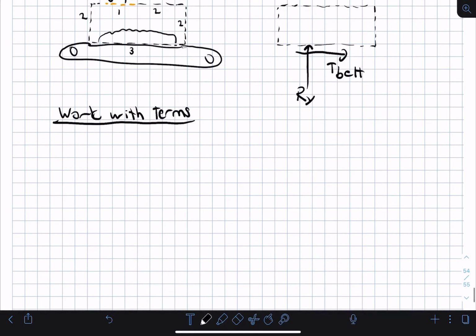Okay, and so we have partial t times the volume integral of rho times the velocity dV in the control volume. Okay, and so here we are only considering the sand, so I'll just do a little subscript s here to note that we are neglecting the air, and I already justified that above.